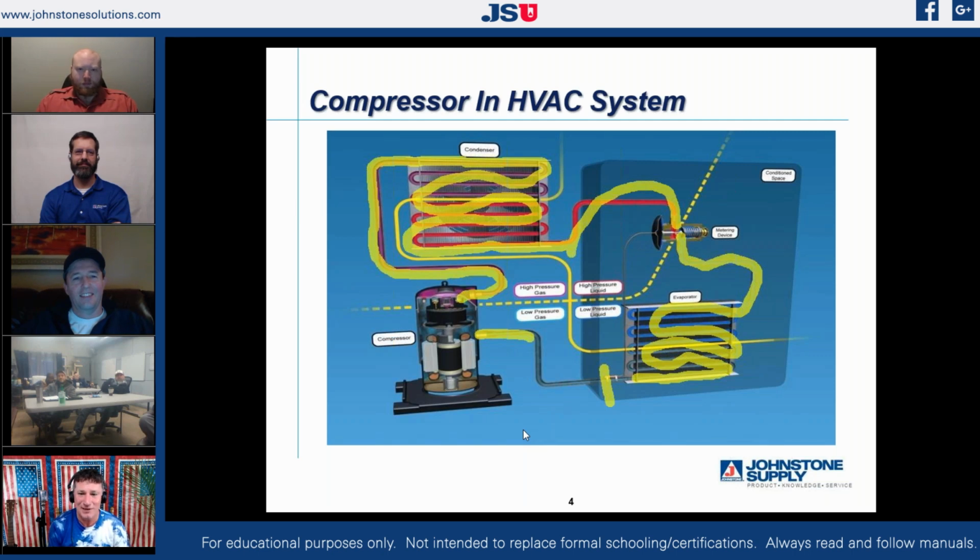So when we come out of that evaporator, we're going to be boiled off refrigerant. And then we're just simply going to measure it and make sure that we have completed that boiling cycle so that we've made our coil efficient and we have gotten rid of all of our liquid, because liquid refrigerant is an incredible solvent when it mixes with oil. If we get liquid refrigerant back to our vapor pump, we're going to do destruction in one of two places. We're going to destroy our pump, or we are going to destroy bearings in our motor. Because remember, a compressor is a two-part assembly. It's a motor driving a pump.